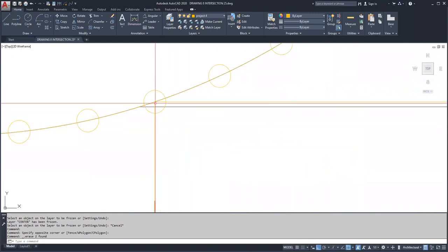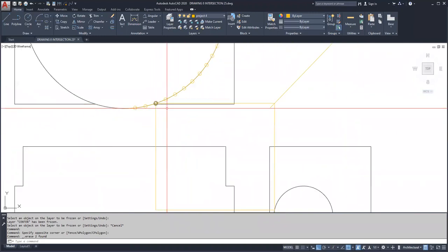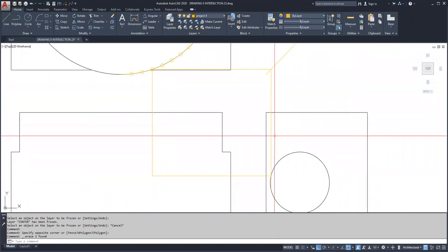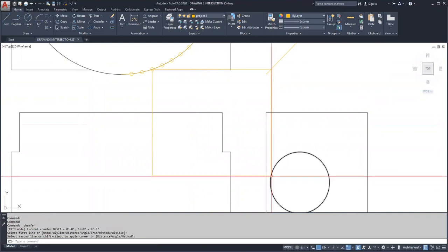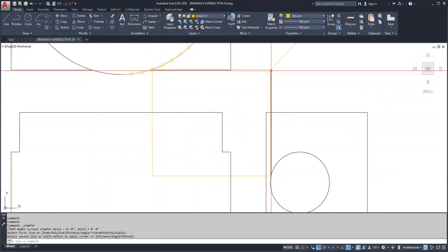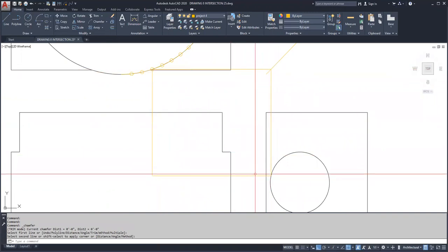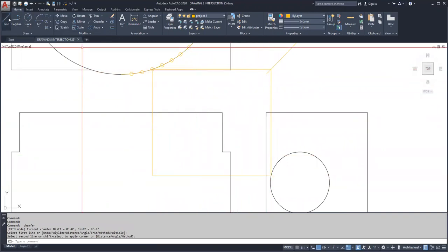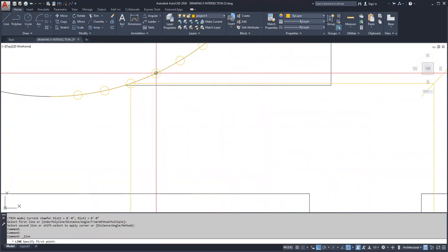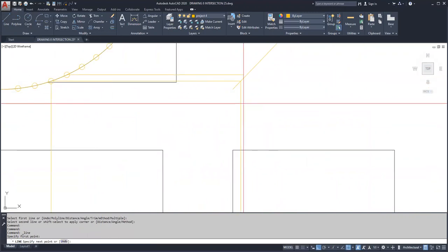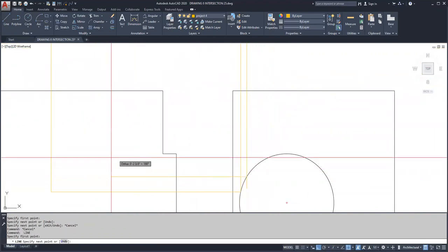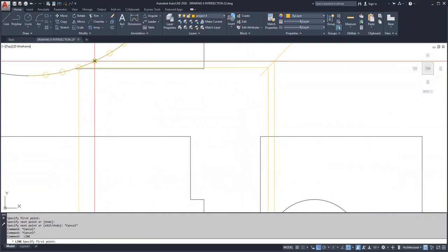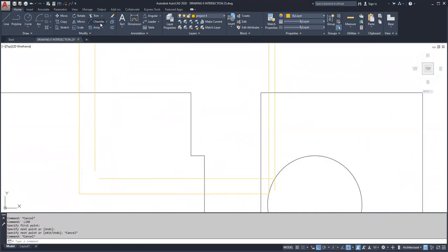Really, so far, what I did was start from one of these points, hit that 45 line, drop down, hit the circle, where it bounced off the circle, it met back up with its original friend to create this box. So let me repeat that process with the next one. Go to the next point, hit the 45 line, drop down, hit the circle, go towards the left, drop down from the original point, and let's make that a nice clean box.